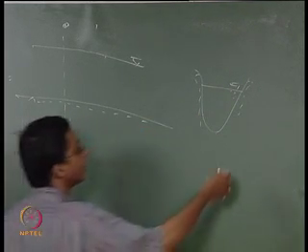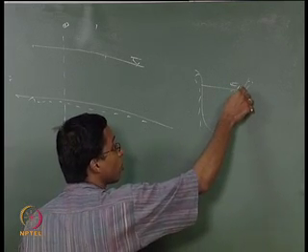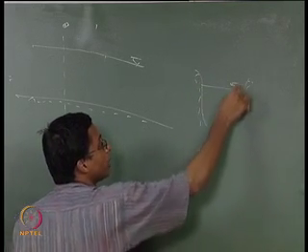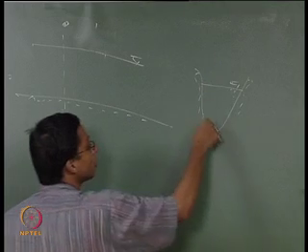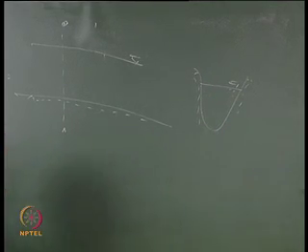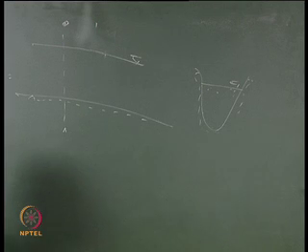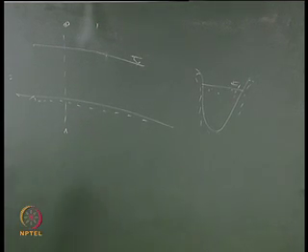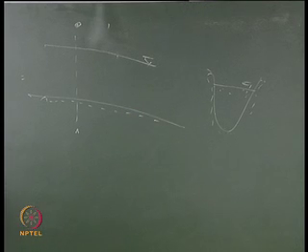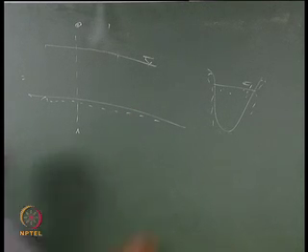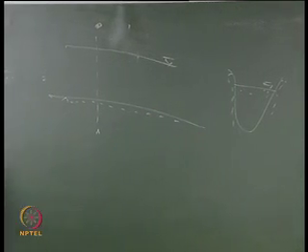It will differ, especially due to the shear stress components, due to the interactions with the boundary walls. There will be shear stress, and definitely the velocity will be different in different parts of the cross section. So, you have to compute average velocity from the sections using mathematical methods.